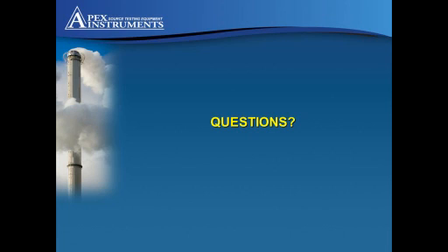There's another question here that asks: is there an opportunity to input moisture stated during the flow RATA and be used as a static number? Yes, it can take the last validated moisture measurement, but I'll give you an update on that. We are pursuing EPA to give us an answer on this, on the collected moisture volume during the sample run.